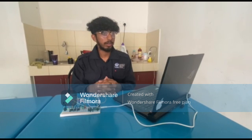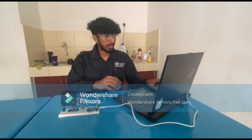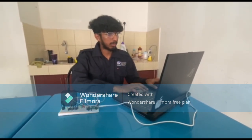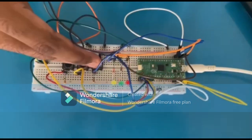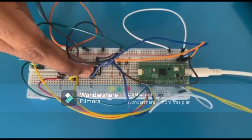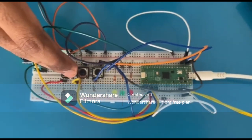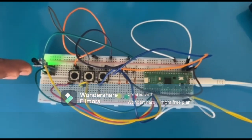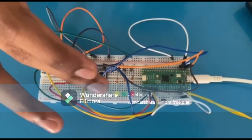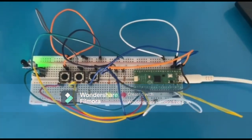Today I will be explaining about my assignment 1, which is the sliding gate automation systems. This is my circuit, and now I will be running the code. As you can see, I have used switch 1, switch 2, and switch 3. Switch 1 is the control panel, the second is for closing, and the third is for opening. This IR sensor is used for motion detection, and there are 3 LEDs to indicate whether it's open, closed, or motion is detected.